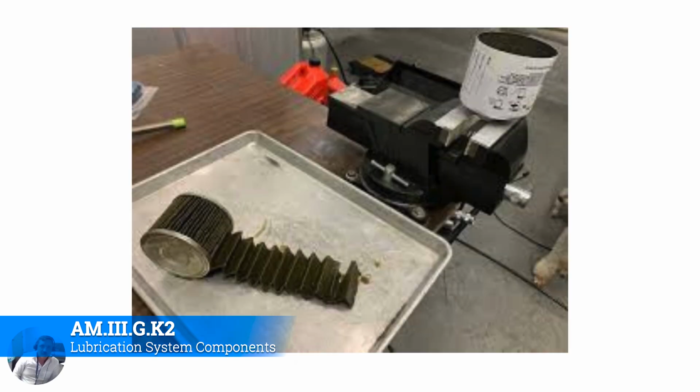Typically with a car engine, you're just going to throw the filter away. Nobody really breaks the filter apart to inspect it. But on an aircraft engine oil filter, you're going to take it off, cut the actual filter element out of the housing, and extract it. We're going to show you how to do that in class. Then you take an X-Acto knife and score the filter housing on either side, and then pull it apart.